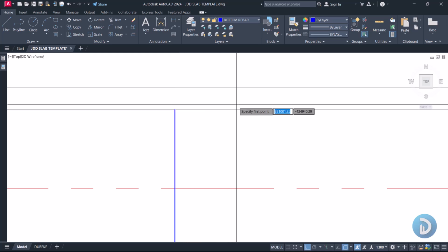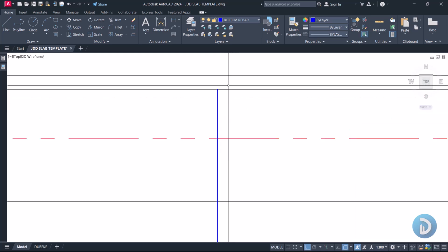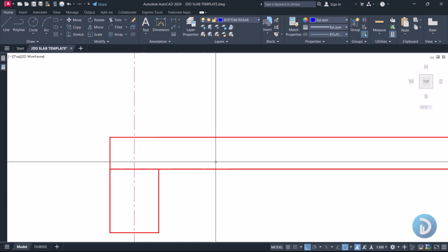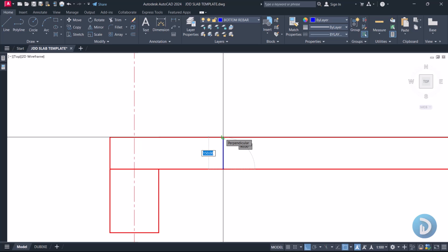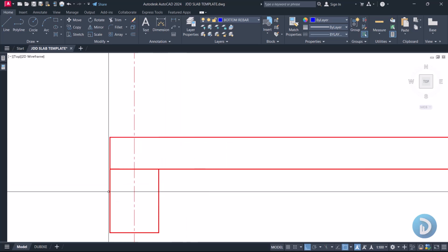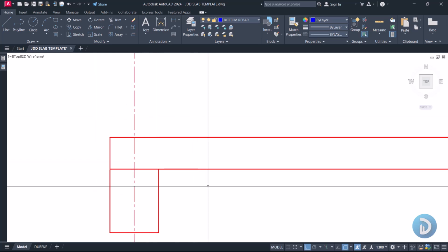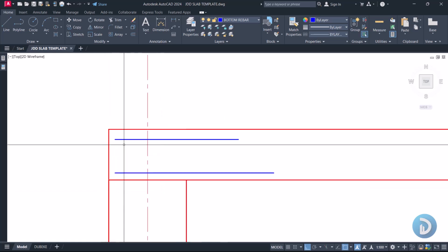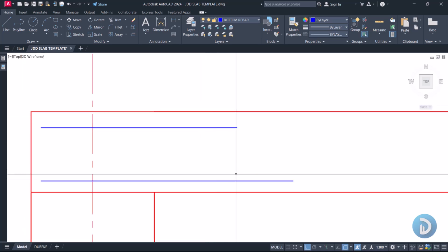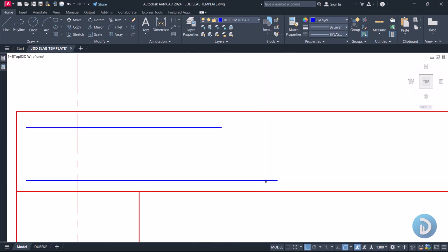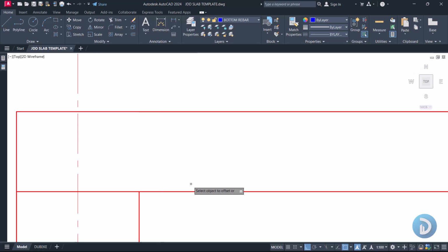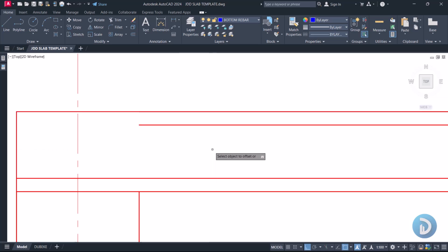So for this to return as a top bar into this panel, there has to be a bent up length here. So let's take an illustration. This is our slab of 150 mm thickness, and over here we have our beam. So for the fact that we are at a restrained end, if we want to get this bent up length that will come from the bottom bar and will return as a top bar, all we need to do is subtract our concrete cover from the top and subtract the concrete cover from the bottom. Then the reinforcement will run directly on this concrete cover, then it will return between this space. So if we offset a distance of 25 from the bottom and also from the top, we are left with our bent top dimension as 100 millimeters.